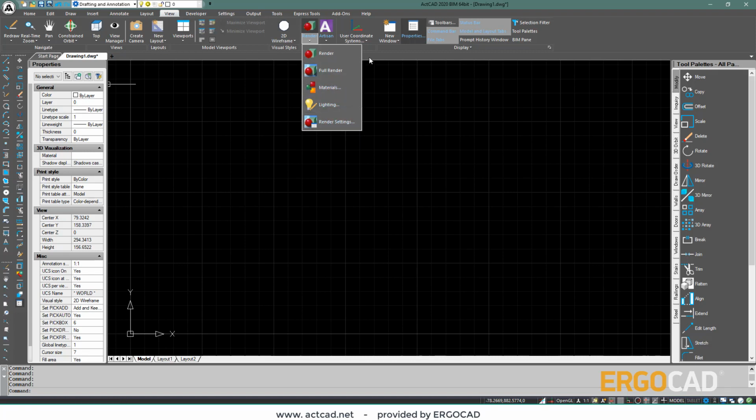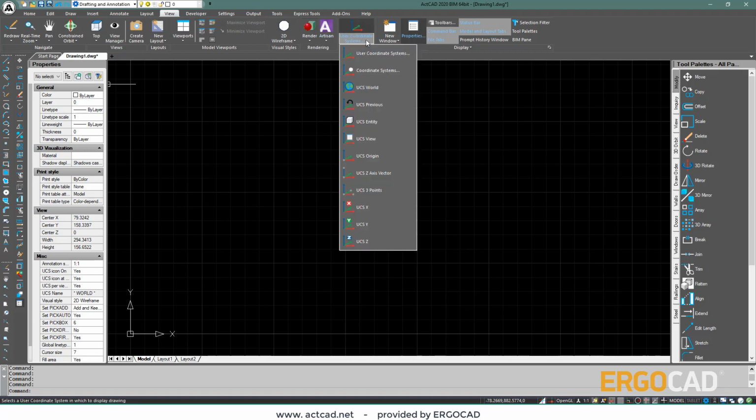A very important command is the UCS, that is, the ability to modify the axis system by the user. This new system can be based on a single point, the world coordinate system and more. The start of the WCS is at the bottom left of the drawing area, where you can see the coordinate system icon, which shows the positive directions of the axis.